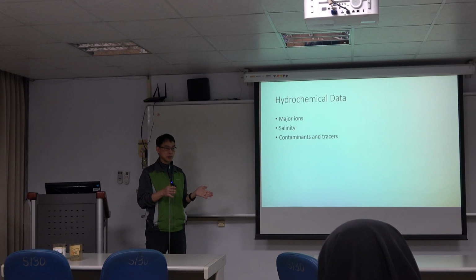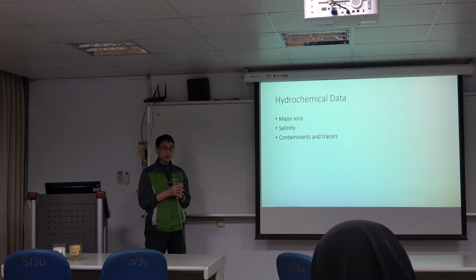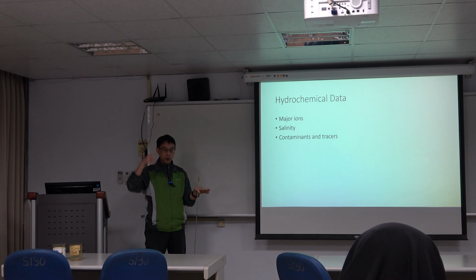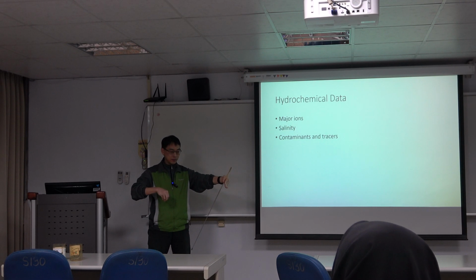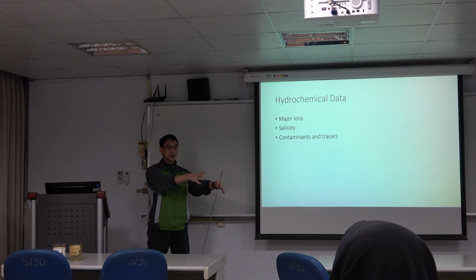And for sediment, it's really easier because sediment is more homogeneous. But if you use a tracer in rock systems, it'll be very, very dangerous because the fractures are uncontrollable. Okay, you don't know which fractures connect together. So you put the tracer here, even 10 meters away, you cannot find anything.